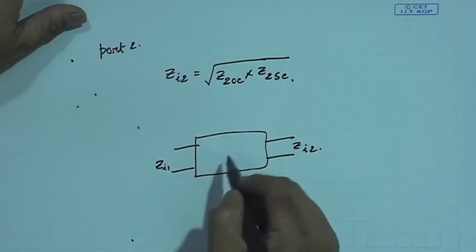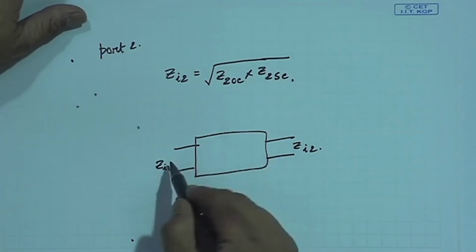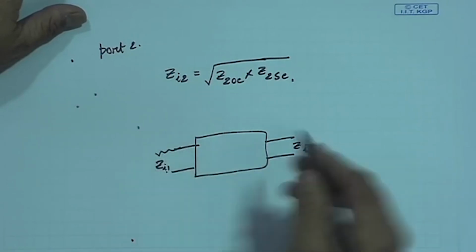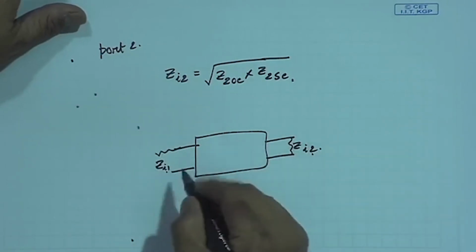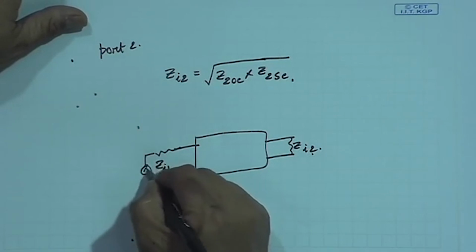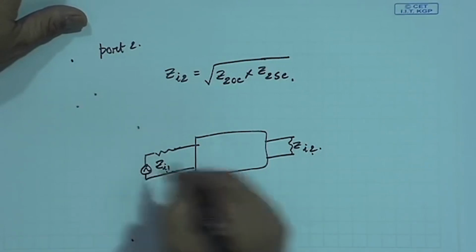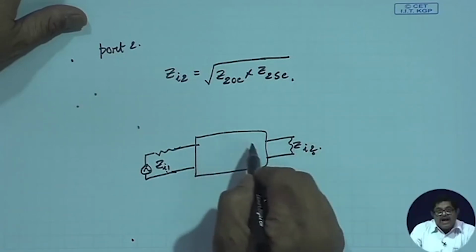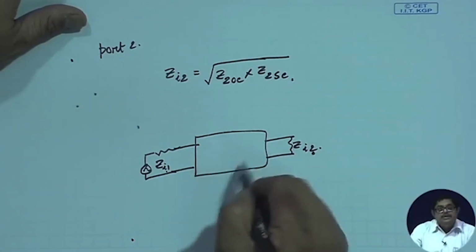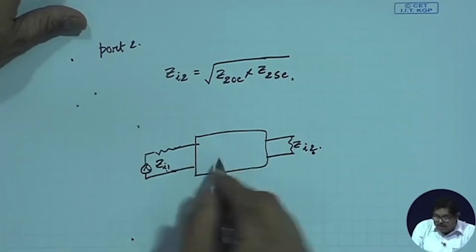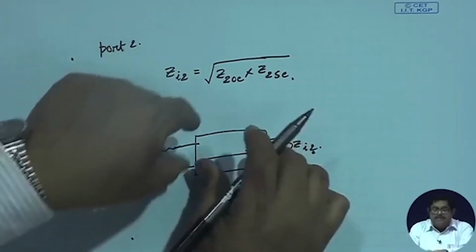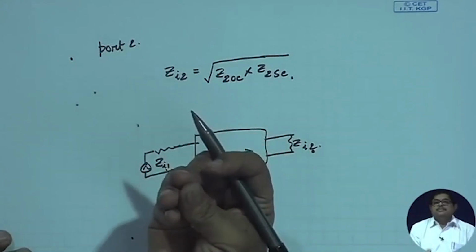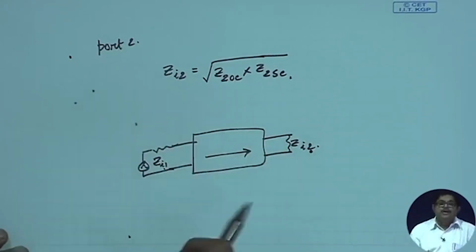Also you see, with this I require to know that by these Zi1 and Zi2 terminations, Zi1 here, Zi2 here, I have ensured that I am delivering maximum power to this load. But I am assuming that here there is no loss, but the power is flowing in this direction. It may so happen, since I am using reactive elements, power may be locally confined, that is not flowing there.